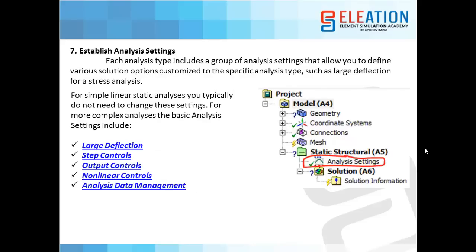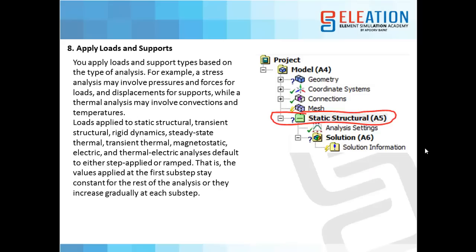Then we define analysis settings where we apply nodal forces, nodal constraints with some displacement constraint, rotational constraint, direction of the forces, magnitude of the force, location of the force. These things we define in analysis settings. Then we define some of the different loading conditions.